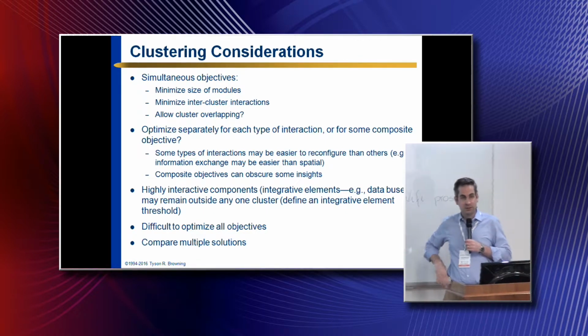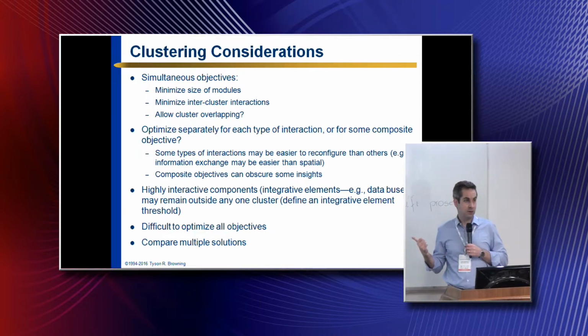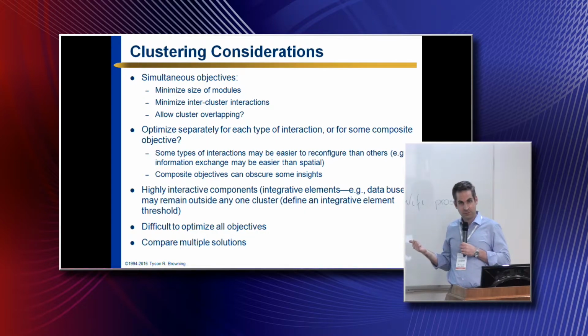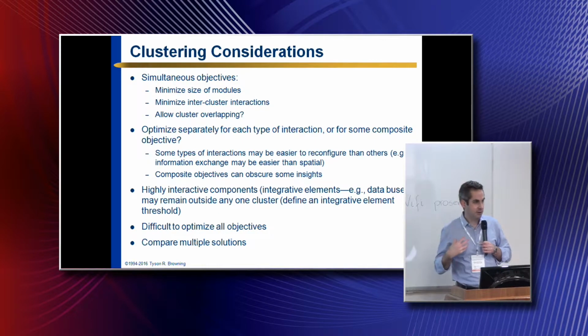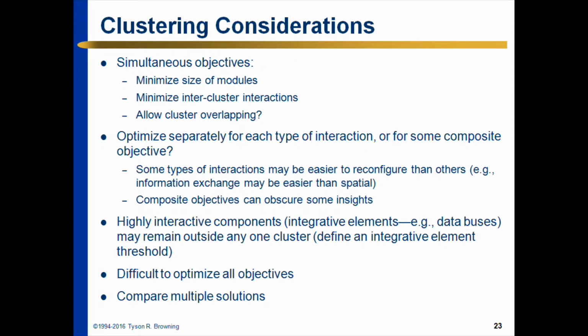And then notice that we just clustered the material flow interactions from that automobile climate control system. Maybe we get a different answer if we cluster just the energy transfer relationships. And maybe we get yet another answer if we cluster just the spatial adjacency relationships. And maybe a different answer if we try to cluster that original DSM that had all the types of relationships at once. So again, is there really one right optimal answer? Not usually. Usually there's a lot of competing criteria, and you're trying to come up with some result that, rather than really optimizes anything, just kind of satisfies everyone at some level.